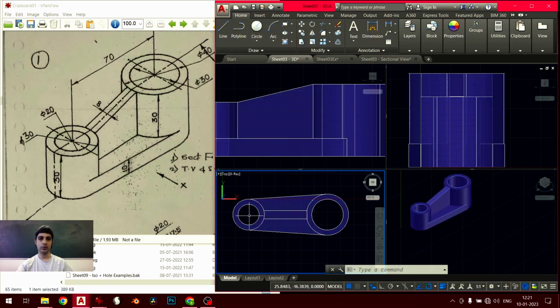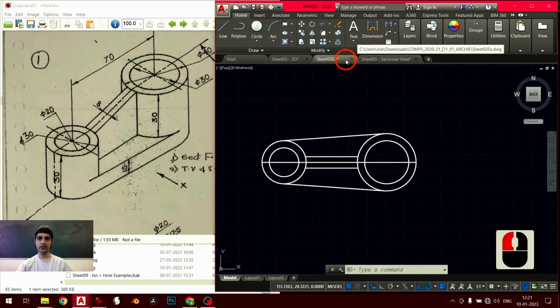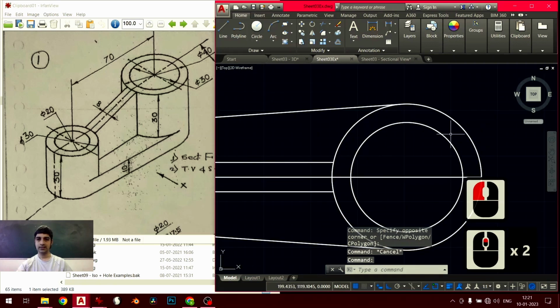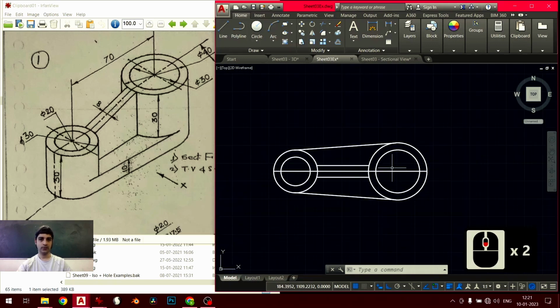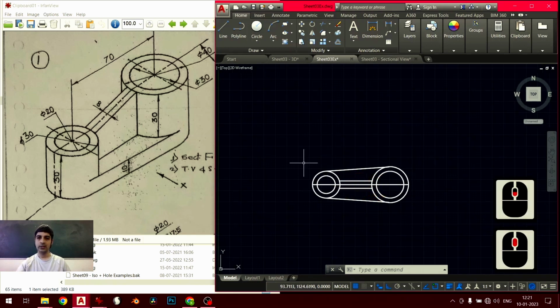What we can't represent in an orthographic drawing is the differentiation between solid objects and hollow spaces. So here, this concentric circle and this little circle inside, you can't differentiate between in terms of what is solid, what is hollow. There are ways of doing that, but we don't really concern ourselves with that in orthographic projection. And of course, information about this will become clearer once we construct the other two views.